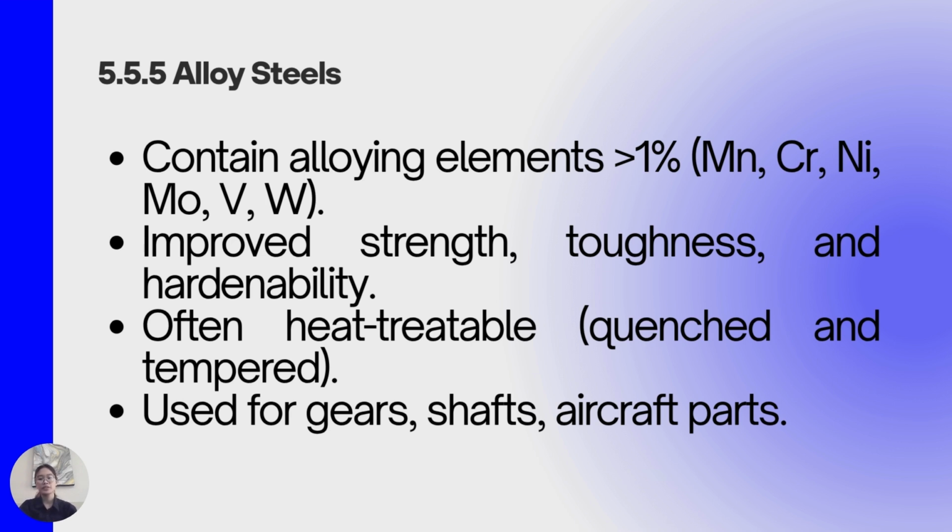However, alloying must be done carefully. Adding too many elements can increase costs and reduce reliability or machinability. Therefore, modern alloy steels are designed to achieve maximum performance with minimal alloy content, optimizing both material efficiency and mechanical performance. In summary, alloy steel combines the best of both worlds: the strength and toughness of carbon steel enhanced by alloying elements that extend their performance limits. They form the foundation for many high-performance applications where durability, heat resistance, and reliability are critical to safety and function.